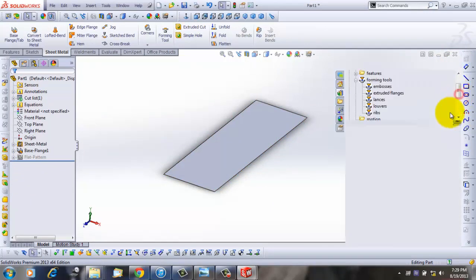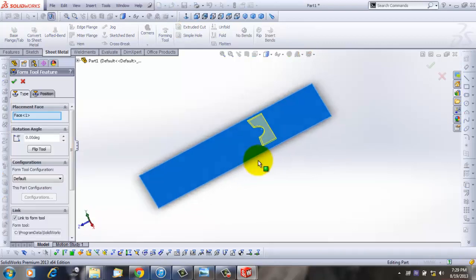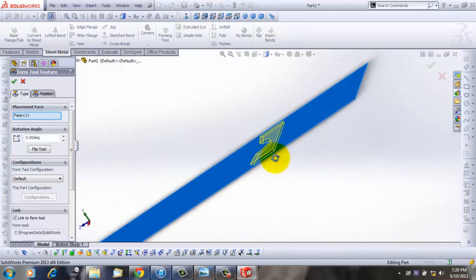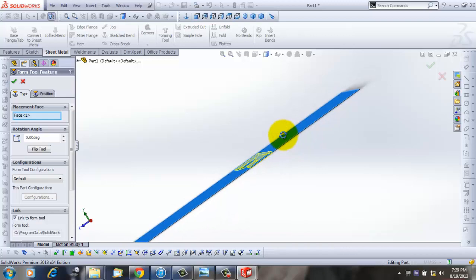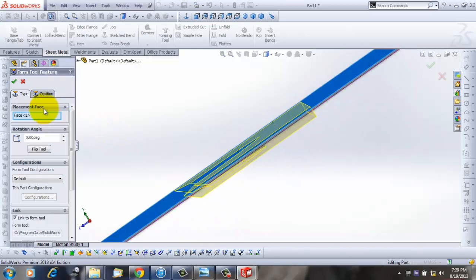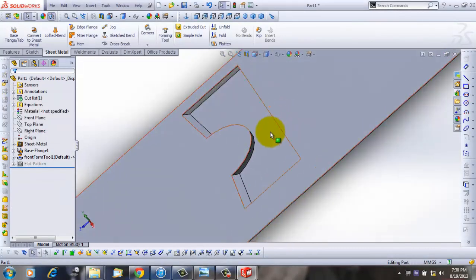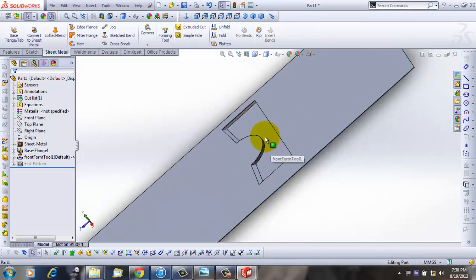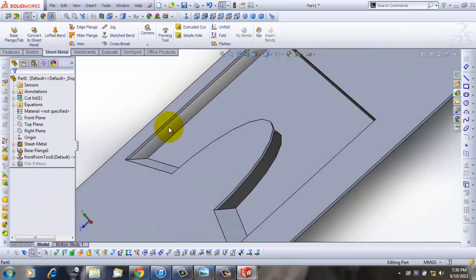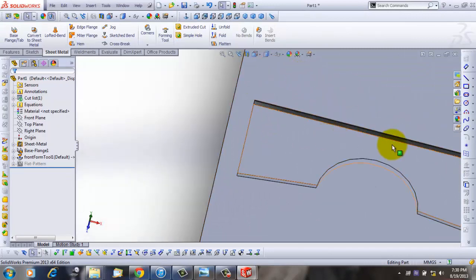I'm going to close it, cancel the save option, and place this tool and see what happens. Now you can see that SolidWorks realizes where I have to start and where I have to stop. It actually takes the whole thing. Now when I apply this and the profile is formed, you can see there is no sheet metal on the red surfaces.